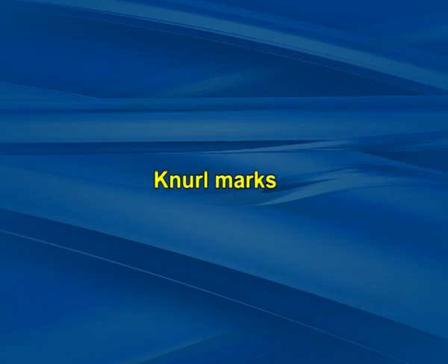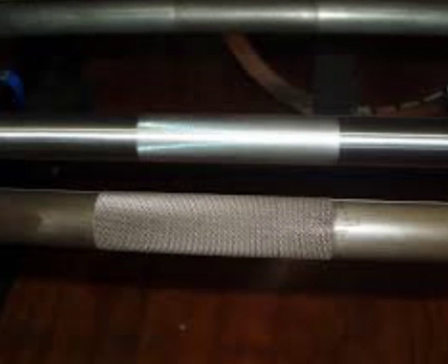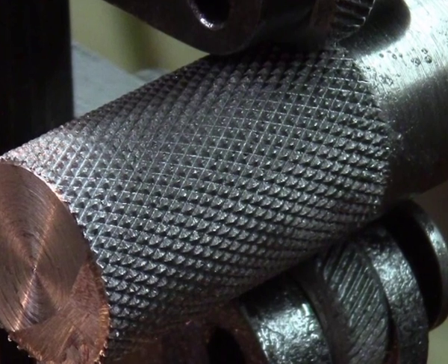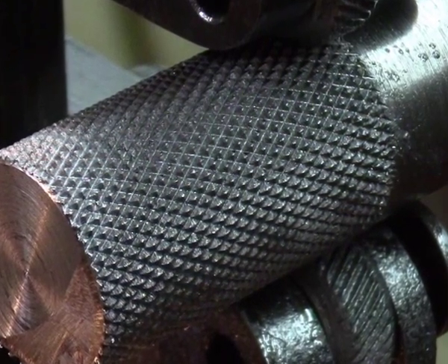Nozzle marks. These apply mainly to tubes but can also occur with narrow necked rigid containers, and are caused by the use of steel nozzle point or printing fingers which grip the container internally in the nozzle or container neck, leaving deep cuts or torn metal. It is possible to obviate these by using alternative devices.